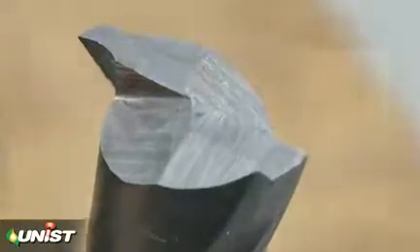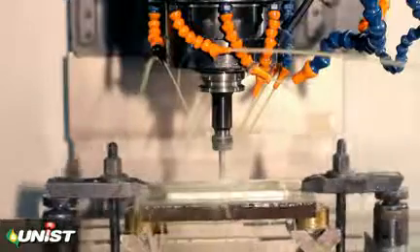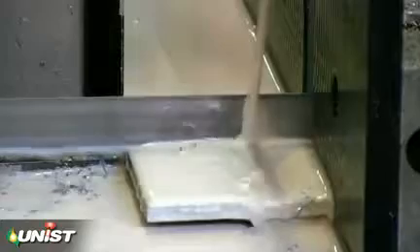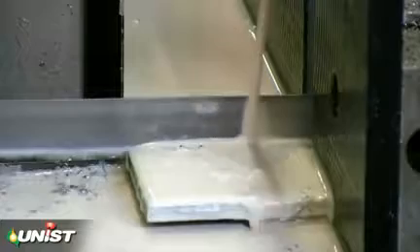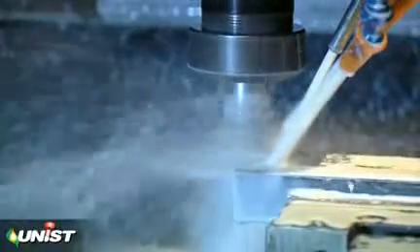Most machinists try to cool things down by flooding the cutting tool and the workpiece with coolant. This flood method works in that the coolant is able to absorb a lot of heat. But this method only eliminates the symptoms of the problem, rather than addressing the cause. The real problem to be tackled is the friction, not the heat.